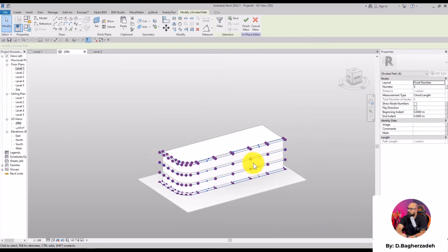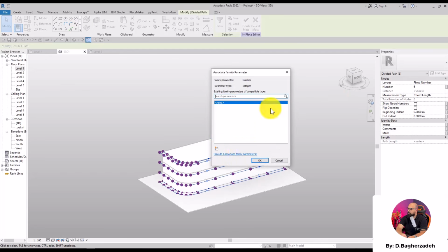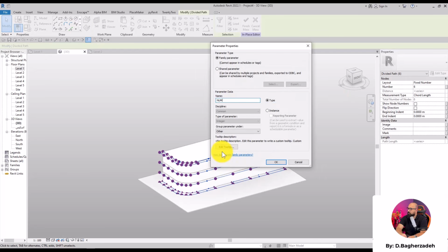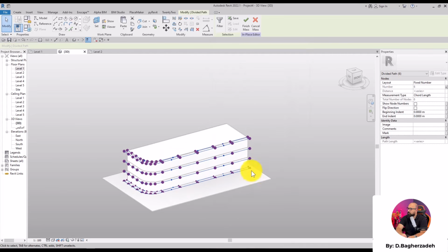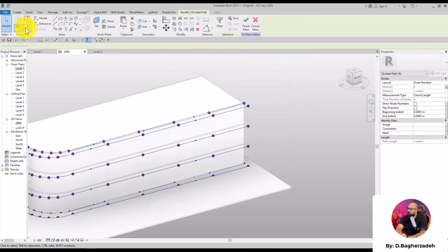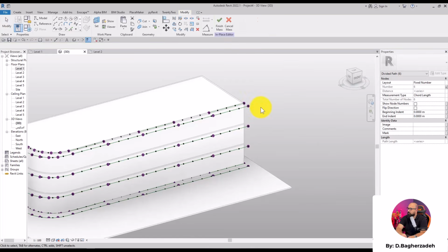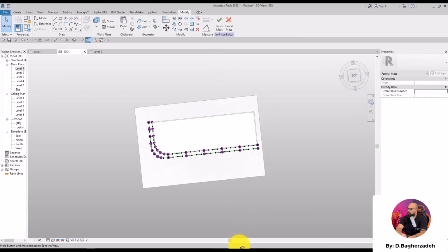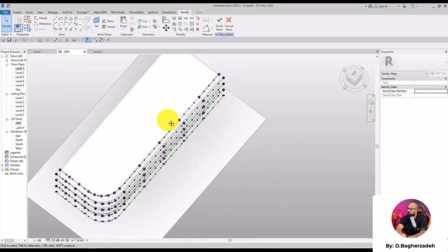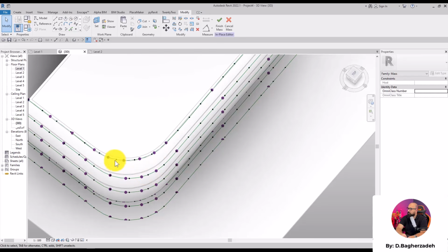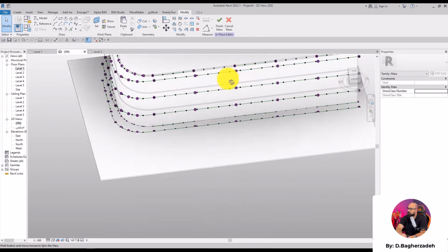And also, I want to have complete control on the number of segments. So, from the number up here, I'm going to go ahead and specify this new parameter, a parameter that I'm going to call number, as you can see. This way, we don't really need to work with UV grids anymore. So, let's try it now. For example, let's set it on 20. How about 30? Now, we have the points, guys, and they are aligned. And by the way, because of the length difference that we got in the curved parts, we might see some angle differences as well. Other than that, everything else seems fine.